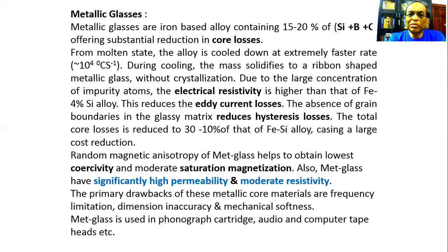During cooling, the mass solidifies to a ribbon-shaped metallic glass without crystallization. Due to the large concentration of impurity atoms, the electrical resistivity is higher than that of iron 4% silicon alloy. This reduces the eddy current losses.